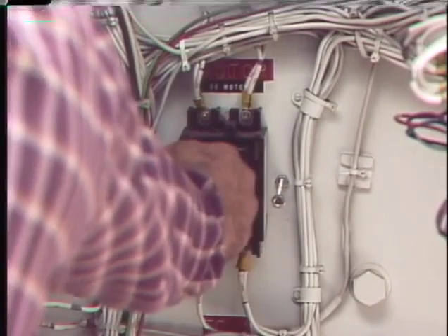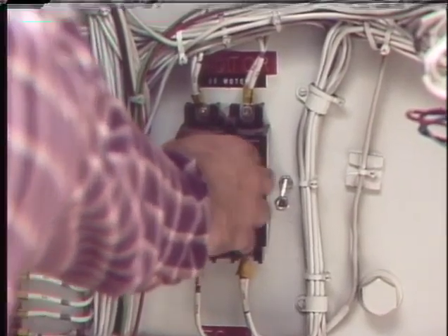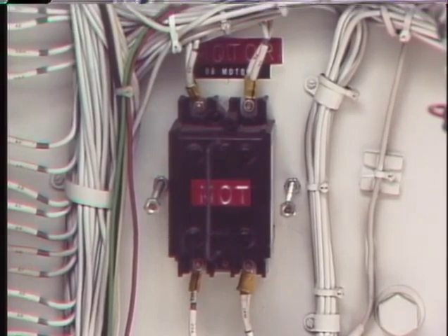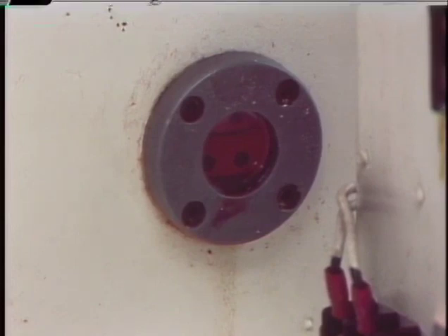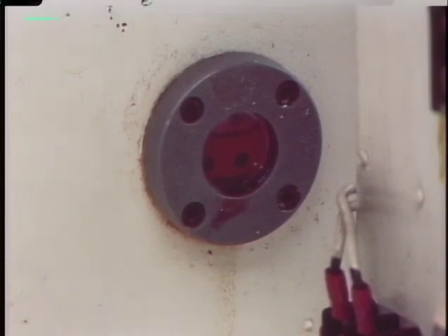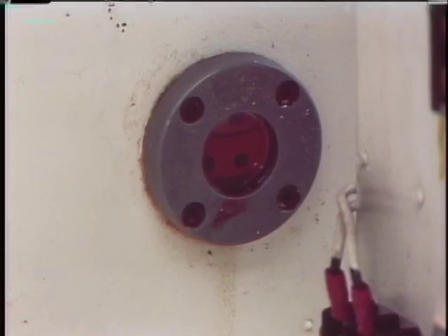After the precharge pressure has been checked and gas added, if needed, the motor can be re-energized to restore system pressure to normal. With system pressure at normal, another fluid level check should be made. This time, a sight glass at the bottom of the reservoir is checked. Fluid should be visible. If it isn't, bleed the system to zero and recheck the level at the upper sight glass. Then recheck the precharge pressure.